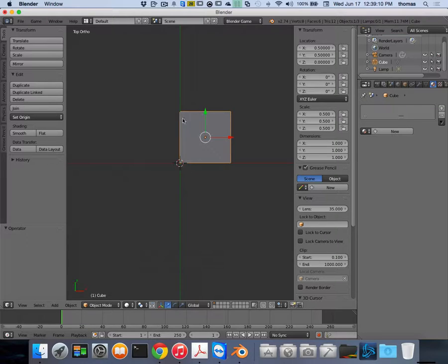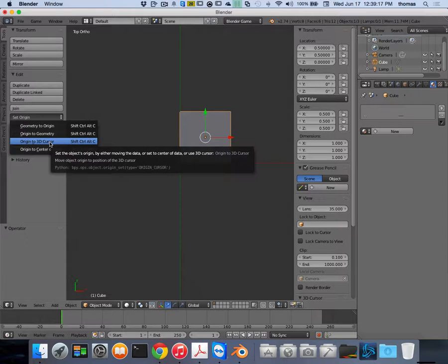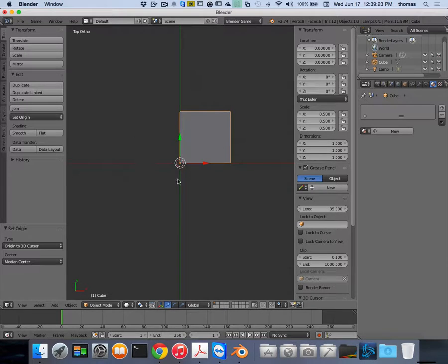So in order for me to set my origin to the bottom left-hand corner, I'm going to go set origin to 3D cursor on the left here, or Shift Control Alt C. It's a big long shortcut. When I do that, now if you notice, the left edge of my object is where the origin for my object is. Well, that's good partly, but I want it to go to the bottom left-hand, this vertex right here. That's where I want it to go.